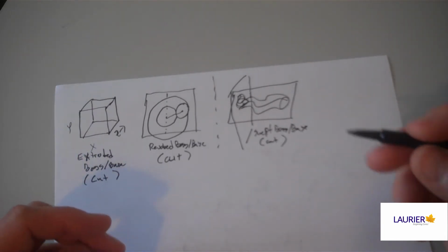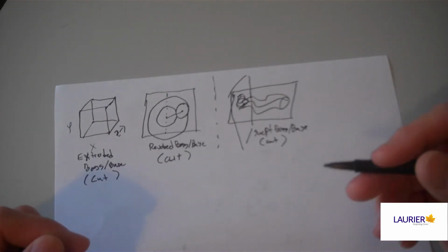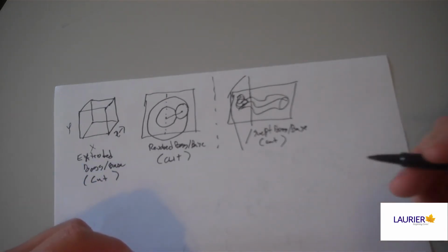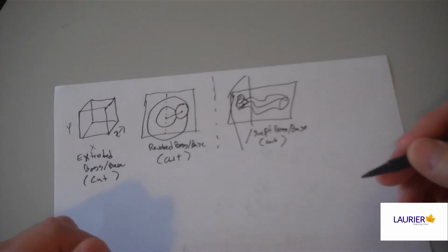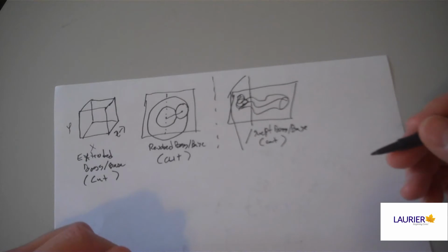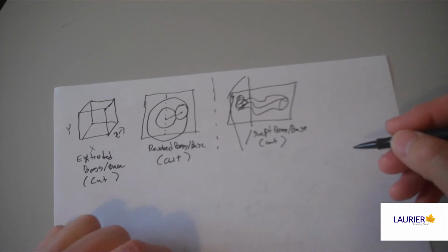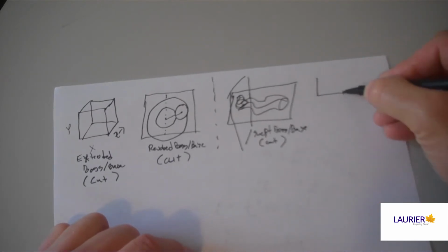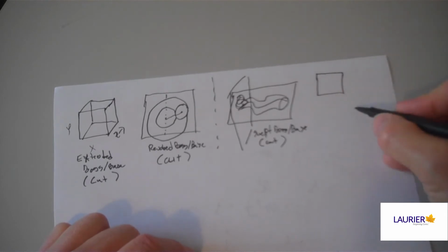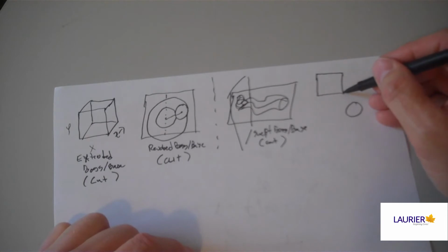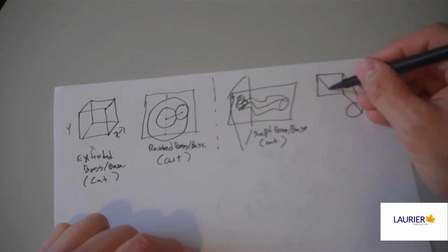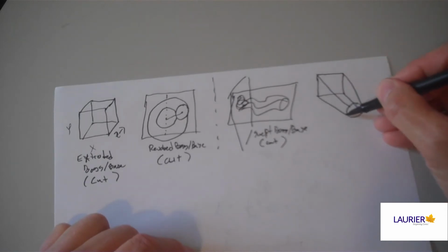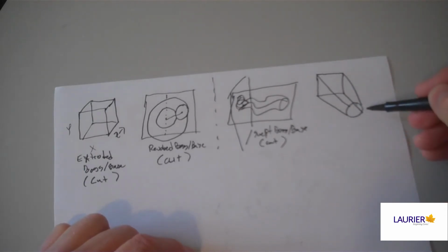So one of the coolest things that we can do in terms of making shapes is to make a shape on one plane, make another shape on a different plane, and get SolidWorks to connect the two of them into a solid. This is very helpful when making more organic shapes. Shapes like a human arm don't tend to be made from perfect geometric shapes, and they don't tend to run in straight lines or perfect normals or parallel alignment. This tool will gradually change the cross-section from the contour of the first shape to the contour of the second shape as it fills in or removes the material between the two along the way.